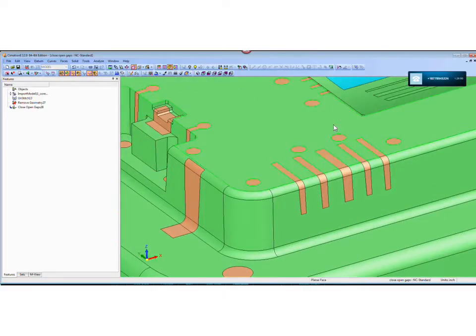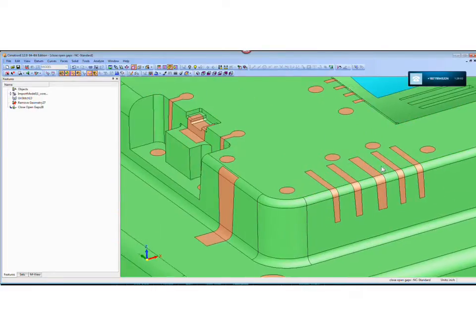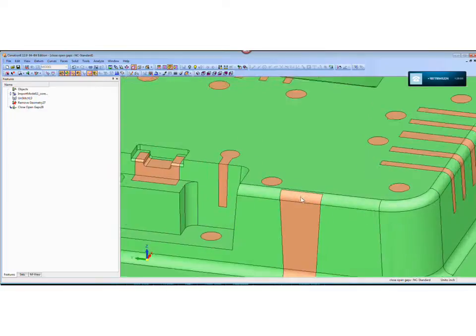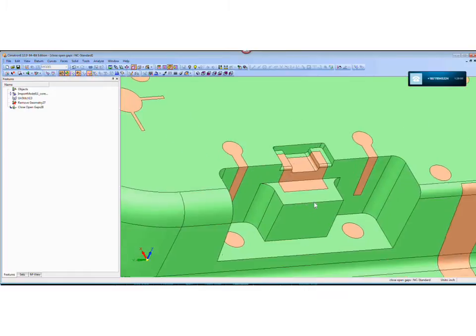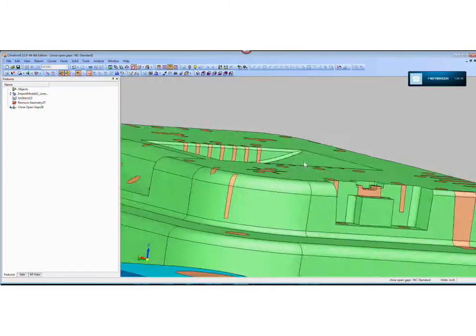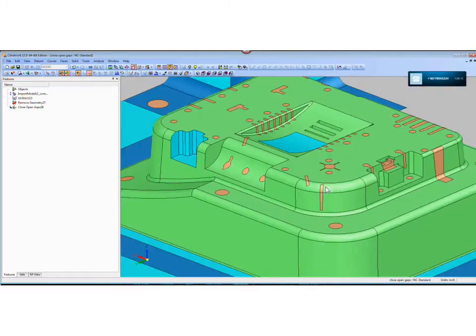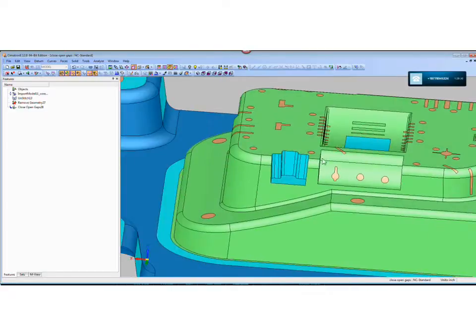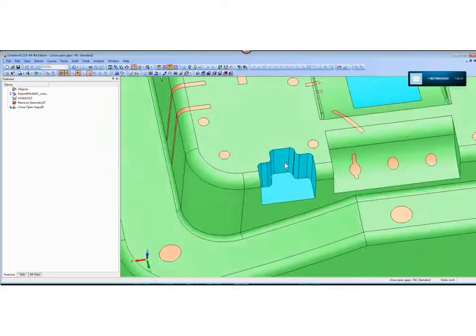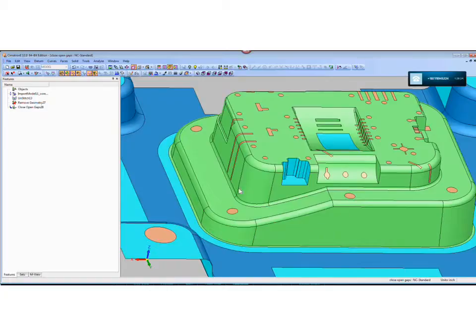And this is a real time saver for putting patches over models. And it doesn't matter if this came from SolidWorks or Pro-E or CATIA. It could come in through IGES or STEP. We don't need the history to do things like this. Again, even though this isn't a closed model, I could do things like remove and extend, and I could say I want to get rid of this feature. I can make it go away.